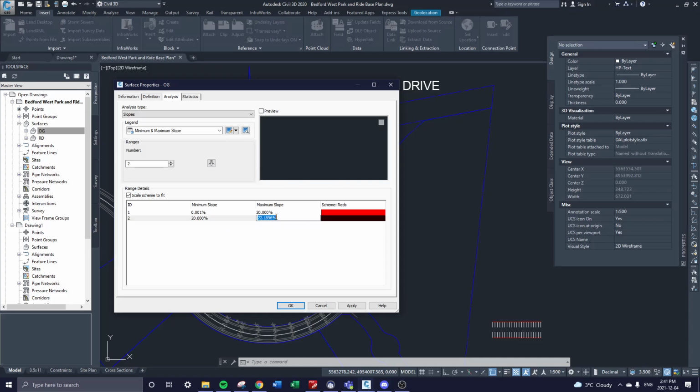If you think about you're trying to make a nice flat or somewhat flat driveway, and you have a hill, you're going to try to avoid that hill because you're going to be cutting a lot more. And when you're cutting a lot more, that's way more expensive. Excavation is the most expensive part of construction typically. So you try to avoid it as best as you can.